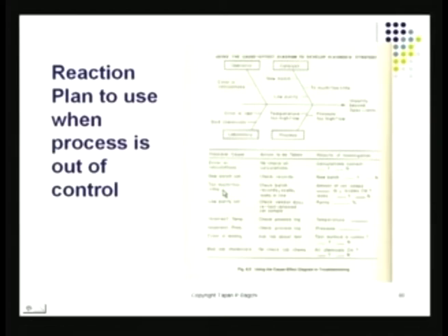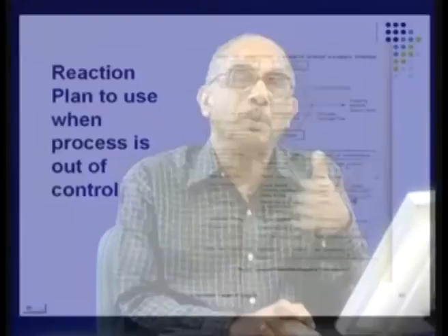Too much quantity added or too little added: check the batch records, check the sheet, look at the scale and so on. Make sure the scale was calibrated, all those things. If that is happening repeatedly, then of course you probably are missing on gauge R&R. That is something you probably should not do, particularly if you're trying to be a Six Sigma production process.